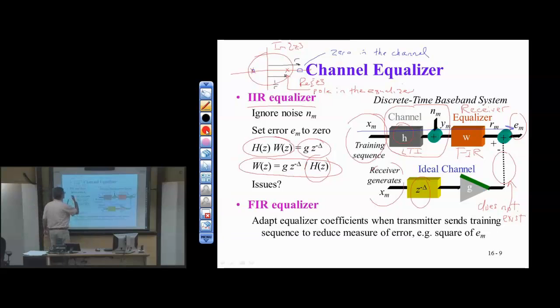All right, let's do that. Just put a couple of zeros on the unit circle. Now what do I do? What's the best I could do? What if I put the poles right on top of the zeros? What happens? Unstable. So what can I do? Put them really close, and what kind of filter do I get? A notch. Remember, a notch filter is all pass outside of the notch frequency and a small band around the notch frequency. So the best thing I can do is to put a pole as close as possible, maybe radius 0.9, but at the same angle as the zero.